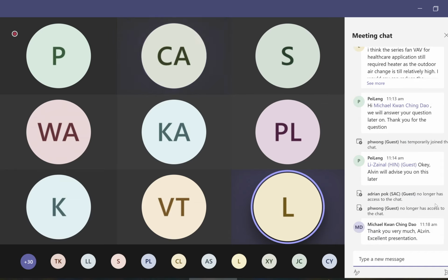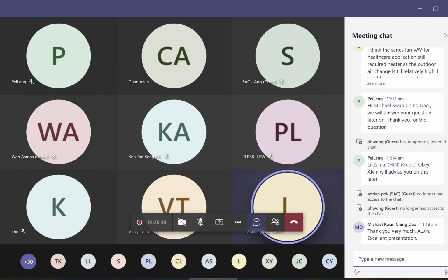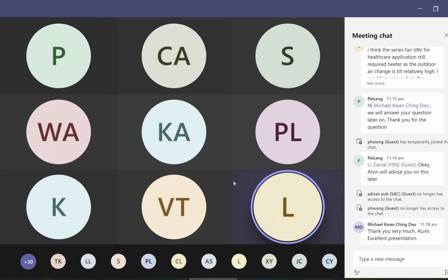I noticed that because the VAV system, the set point will be at the off-coil temperature of the primary AHU. Yes. So due to the static requirement, we know that the affinity law, some pressure we cannot ramp down too low. Then there might be an area that is overcooling. This is a common issue for the VAV. How do you tackle this?